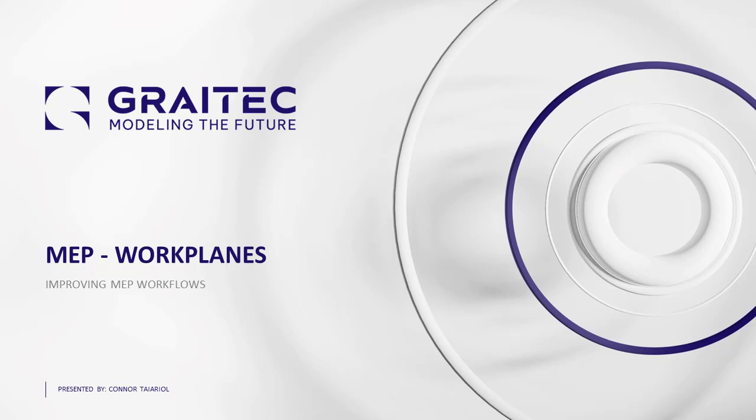place things like electrical panels or tankless water heaters, anything that would be hosted to either a wall or a ceiling. These are typically elements that you're going to be placing onto a workplane. The reason being is if that architect deletes their wall, typically that element, that wall or ceiling, is going to